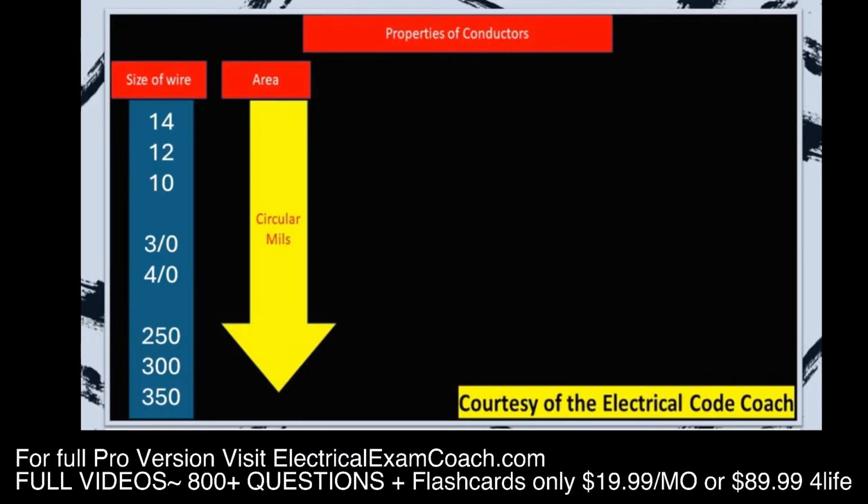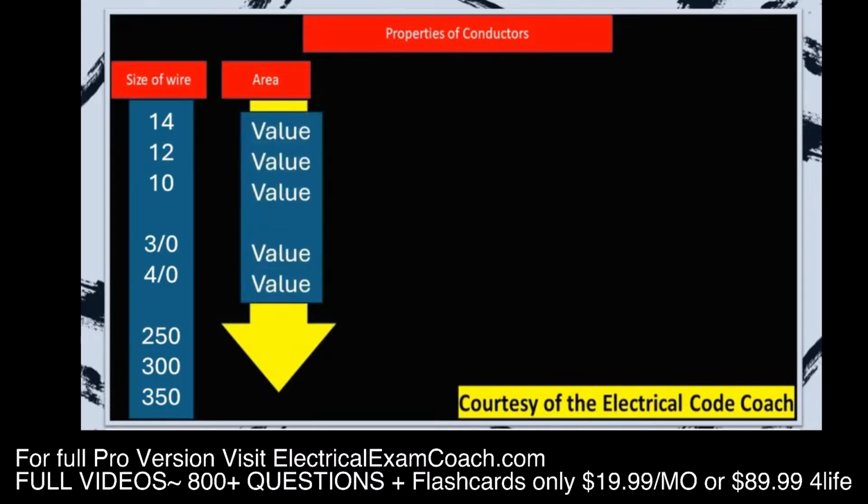In the next column over, we need to be sure to be in the area section because that's where we're going to get our circular mils value. Each wire has a circular mils value. And you'll notice for the first few wires that there's 2 sets of 12, 2 sets of 14, 2 sets of 10. But if you look over, the circular mils are the exact same size. So don't worry about if it's solid or stranded. Just go over to the circular mils. Make sure that you're in the area section under circular mils, and you'll find your value.